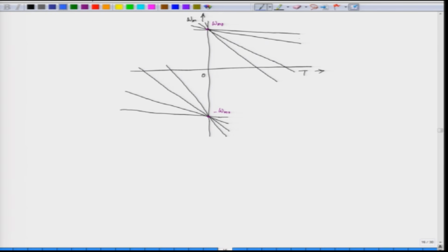So, this is called the forward motoring. This is in the first quadrant, quadrant 1, and this behavior of the motor is primarily called forward motoring, including all this. Now, this part of the behavior is called forward regenerative braking.